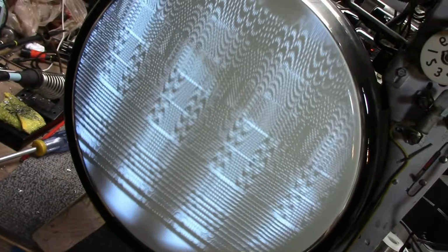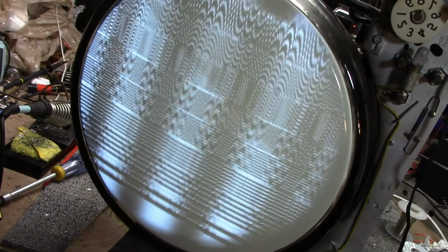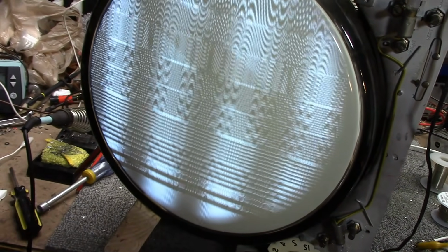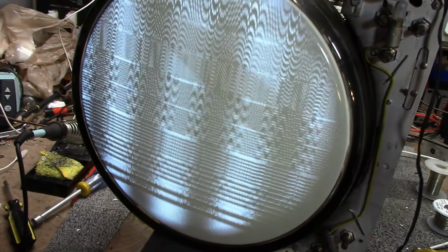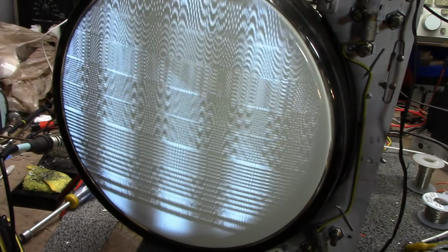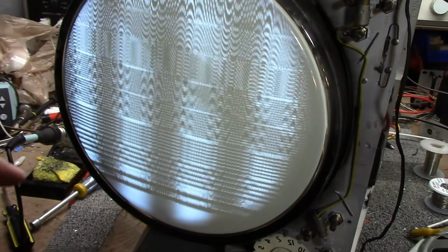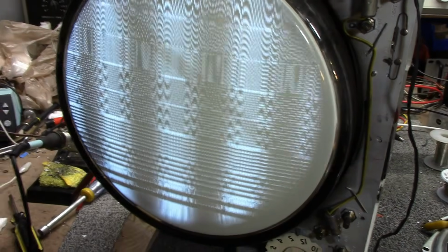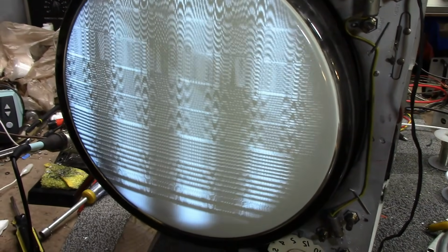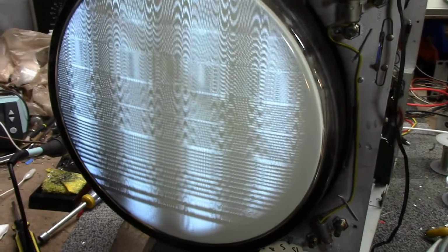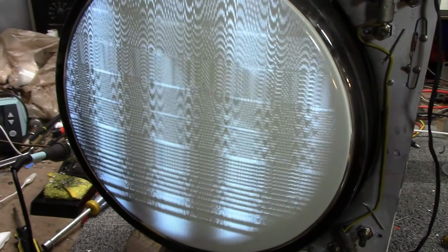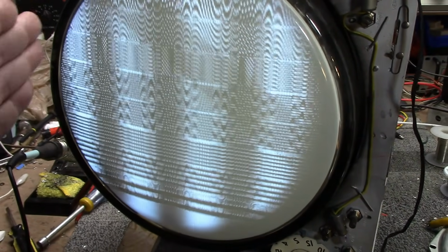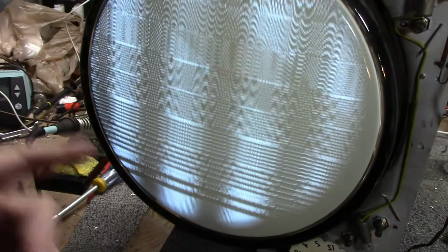Yeah, you're not supposed to get sound bleeding into the video like that. So there are two potential problems. One, the sound IF could simply be off frequency. Two, there is a 4.5 megahertz trap. Somebody asked about this in the comments. I think it's between the first and second video amp stage, something like that. There's a very sharp, distinct trap, a capacitor and inductor in parallel, tuned to 4.5 to completely eliminate any possibility of sound getting into the video. Obviously we do have it, and that's very bad, and this is what happens.